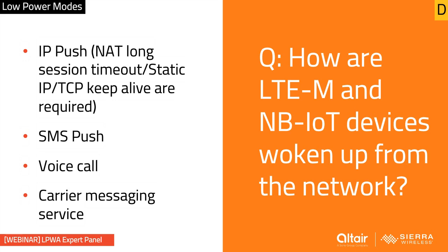The other method is sending an SMS message to wake the device up. The main disadvantage of this method is the cost and the complexity. One, you have to interface with some services that can send SMS messages, and not all cloud vendors can do that today. And two, it costs money, and operators charge for that.